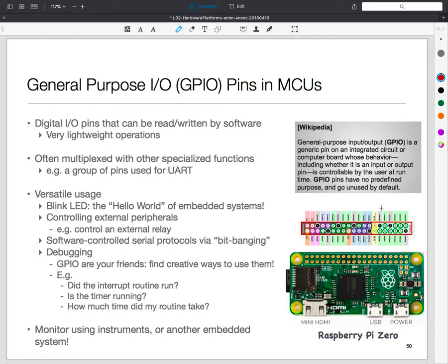So a relay, let's go back out here. A relay is nothing but a switch, and the idea is that in the main part of the circuit we have some sort of a high current, and its control, I want to do it with minimal current. So the control part is what I will hook up to the GPIO, and the main part will be connected to high current or high voltage.